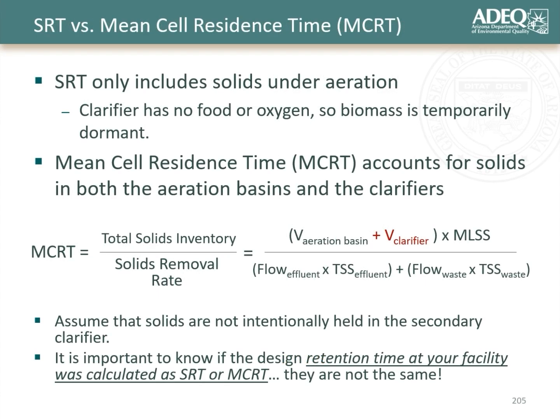So now let's talk a little bit about solids retention time versus mean cell residence time. Solids retention time only includes solids under aeration. So that's the bacteria in the aeration basin, not including those that are in the clarifier that have no food and no oxygen. So they're assumed to be dormant and not actually active in that state. In comparison, the mean cell residence time accounts for solids both in the aeration basin and the clarifier, in which, in the equation above, you include both the volume of the aeration basin and the volume of the clarifier.